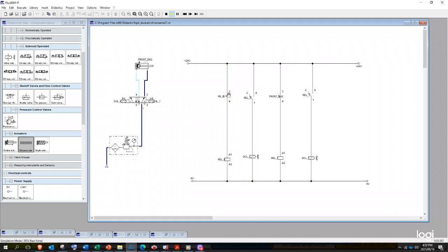Okay, you saw that. I click my push button, current flows, compressed air is flowing. My slide has extended, pushing the wooden boards out of the stacking magazine. I release, check the front end. There's an arrow there on our front end limit switch, which shows that the sensor is on. The sensor is on because why? Our slide has reached its extended position. I release my hand, it returns to its initial position.